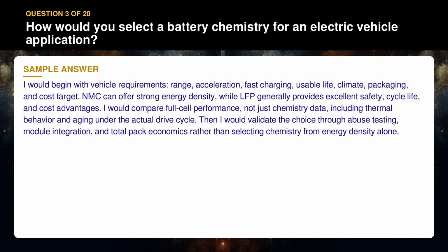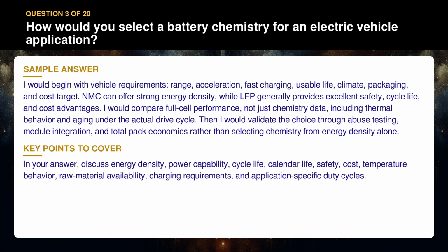Then I would validate the choice through abuse testing, module integration, and total pack economics rather than selecting chemistry from energy density alone. In your answer, discuss energy density, power capability, cycle life, calendar life, safety, cost, temperature behavior, raw material availability, charging requirements, and application-specific duty cycles.